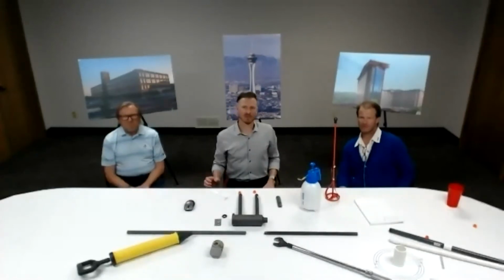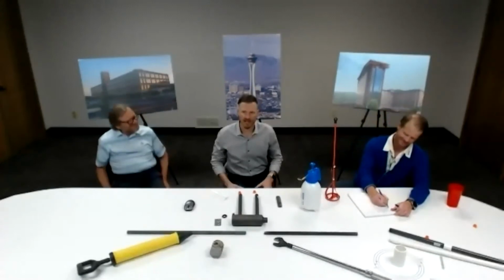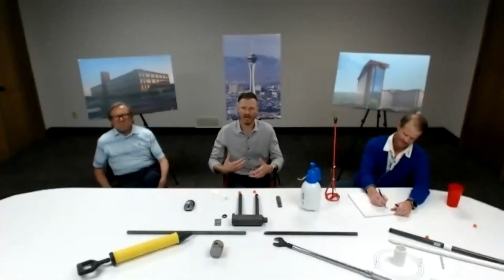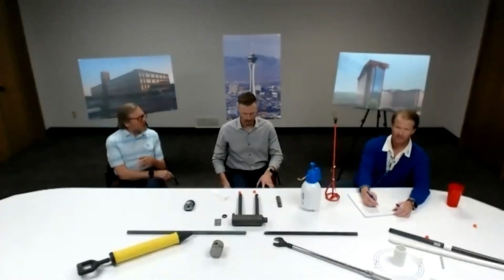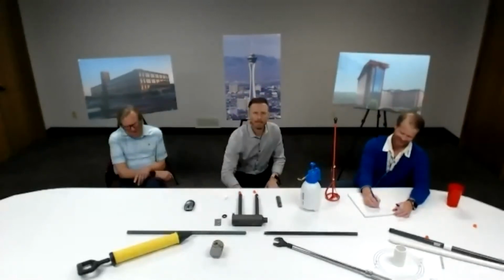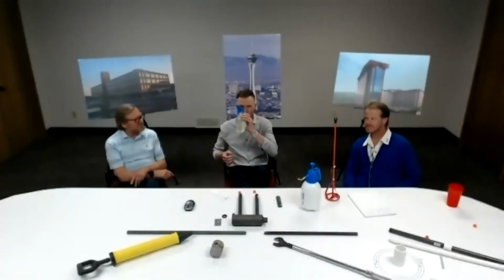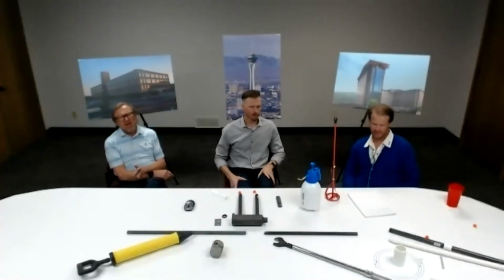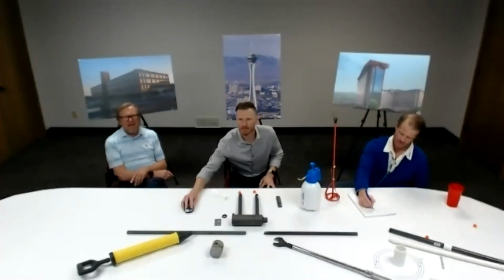This is a question about the grout. What is the preferred brand manufacturer for the cementitious grout that works best to flow? We work closely with Master Builders, they're local here, and we use their 885 grout. If you look at our ICC ESR approval, it includes that 885 grout.